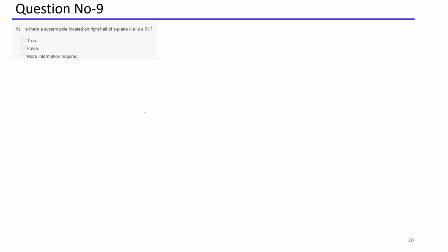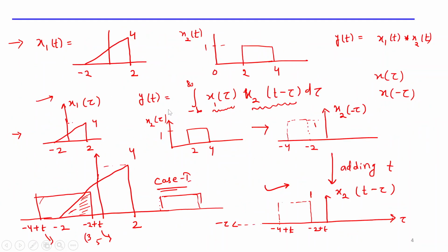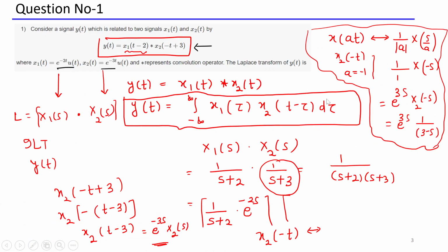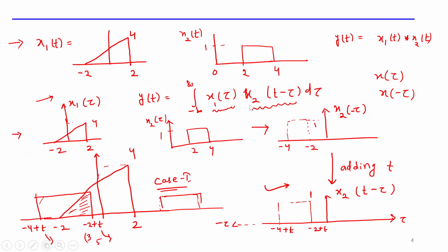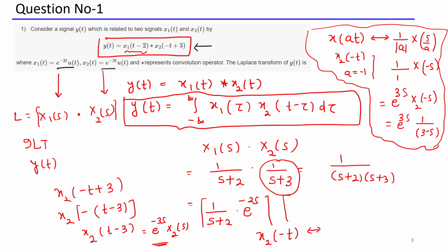The convolution part, everyone is clear, I think, right? How you solve convolution, I told you two methods. One, you can solve using Laplace transformation. And second, you can use inspection, using the formula. Why is convolution in Laplace transformation tedious? Because first, whatever signal is given, you find its Laplace transformation. Then to find the original signal, you have to take the inverse Laplace transformation, so one should apply the formula very carefully. Inverse Laplace transformation always requires partial fractions.